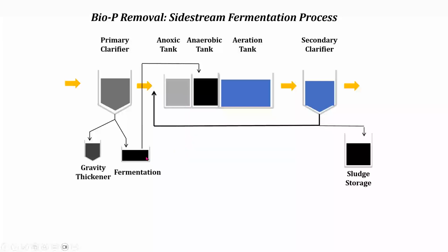So the fermentation now, we're going to take the volatile fatty acids, and we're not going to let the denitrifiers eat the volatile fatty acids. We're going to let them feed on the BOD that's coming out of the primary clarifier as their energy source. So there'll be less nitrate coming into the anaerobic tank, which means the denitrifying organisms, there's no work for them to do. So the volatile fatty acids that flow into that tank are more available to the phosphorus removing organisms. And then the rest of the story, you know, right?